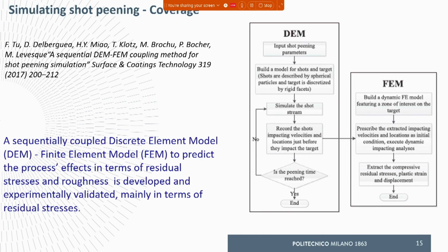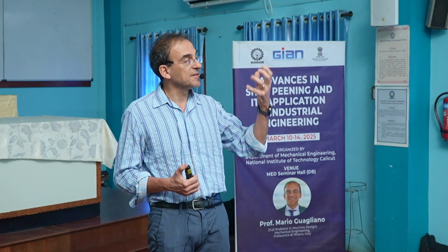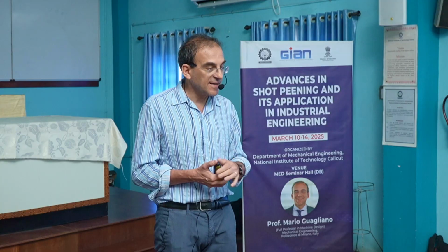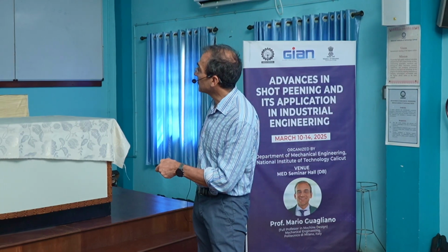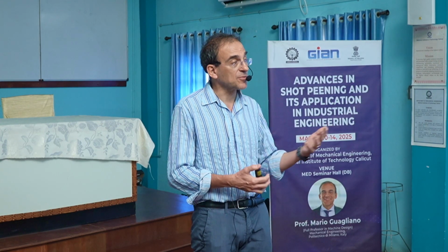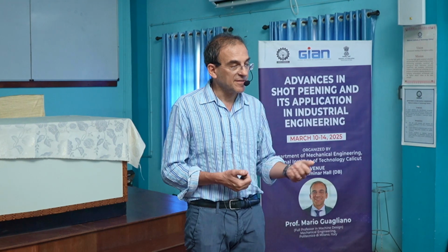He developed this method where he used DEM for assessing the dynamics of the process, for assessing how the shots are impacting the target material, and then the results, as you can see in this scheme, are used as an input of the finite element model that is similar to the one that I described in the slide before.